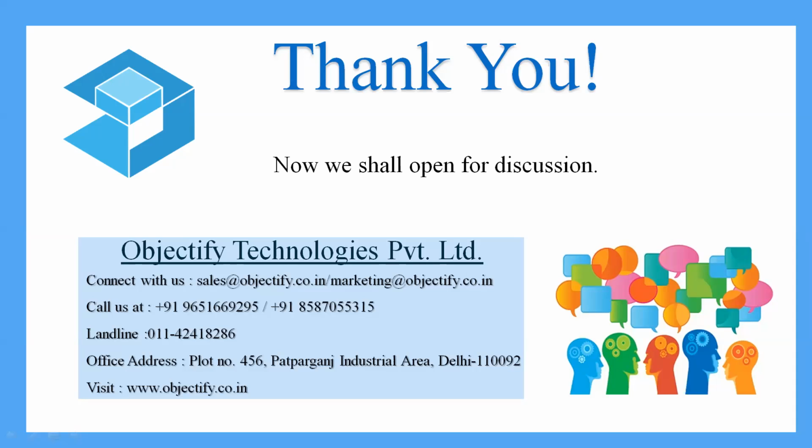So support, in order to deposit the next layer and giving a firm base for the subsequent layer, is essential for few technologies. But in case of metal structures, it is even more essential. It's providing a support, that's the first thing. But on top of that, it has to remove the heat from the body, because compared to polymer, the temperature at which metal melts is quite high.